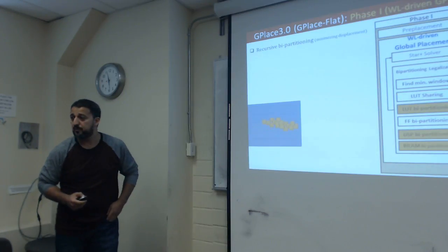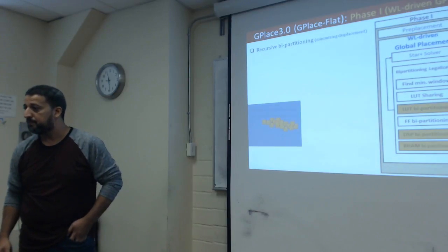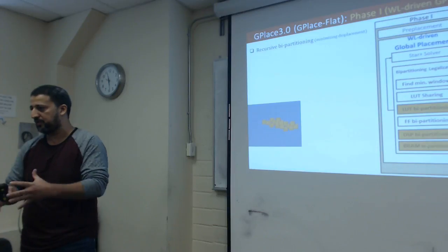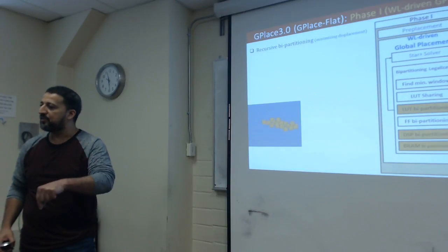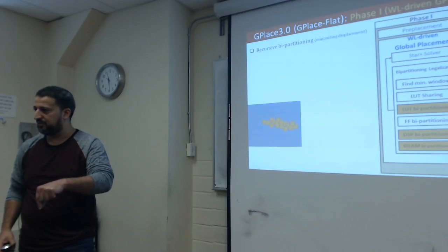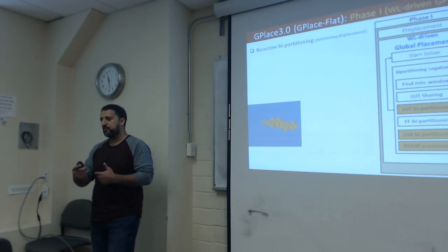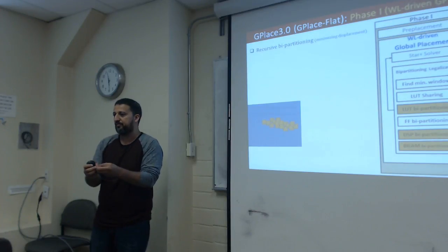So in this case, for each pair of LUTs, you get rid of one of the pair to have just a capacity of 8 for each slice. When you place that single LUT into a slice, that implies the placement of the pair. Yes. And next time, when we solve, those LUTs are free to break.